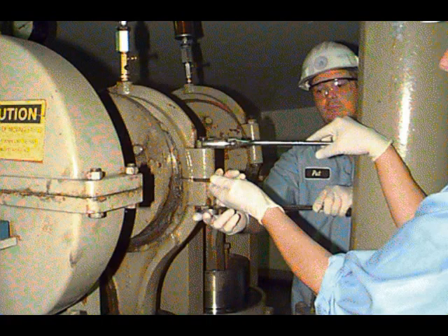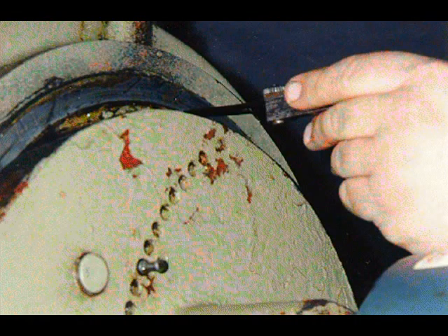Be aware that the connecting rod may require adjustment during the initial weeks of operation of the plunger pump. Brass shims are installed between the halves of the connecting rod. These are removed to take up wear in the babbitt bearing. During the first few weeks of operation, the connecting rod should be checked regularly to maintain 0.13 millimeter (5/1000th inch) clearance between the babbitt bearing and the eccentric.